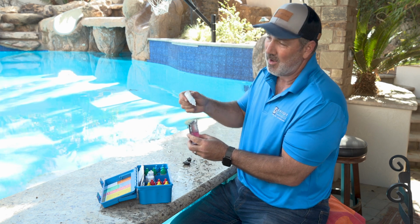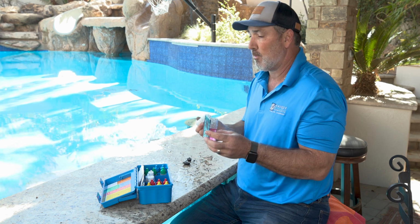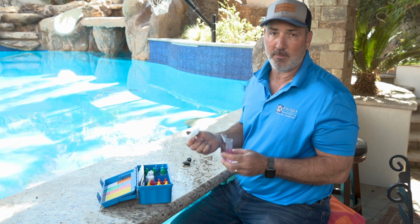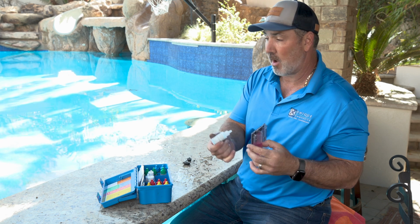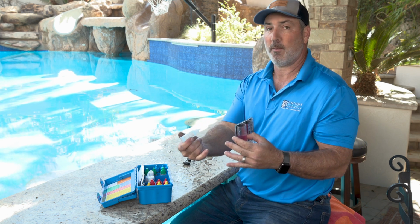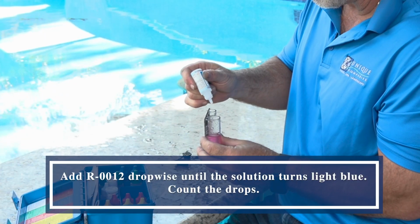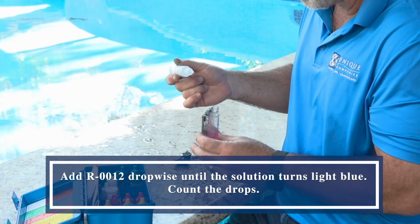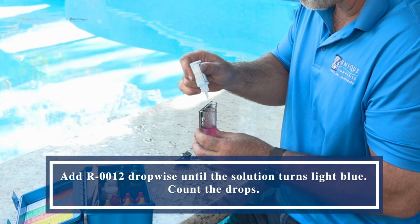So I know my calcium, we want our calcium to be at least 250 when we start up our pools, somewhere between 250 parts per million and 300. So we want calcium in the pool. We want calcium in the pool because we have calcium in our plaster and in our concrete. And if we don't have calcium in the pool, the water is going to want to pull that calcium out, and that's where you start to get the scale. So 1, 2, 3, 4, 5, 6. There's 10, and this will turn from pink to blue, so I have no change.